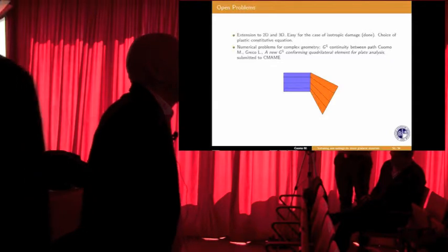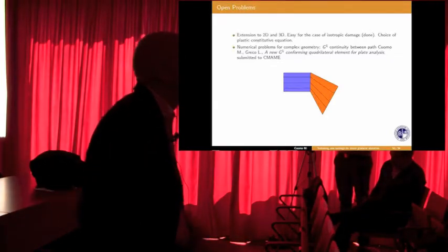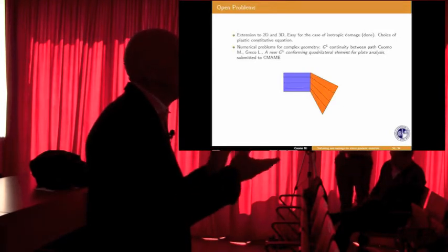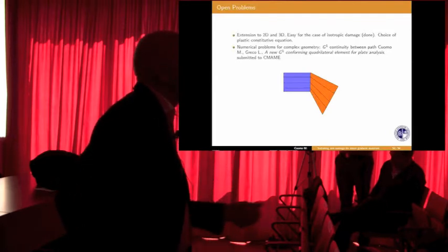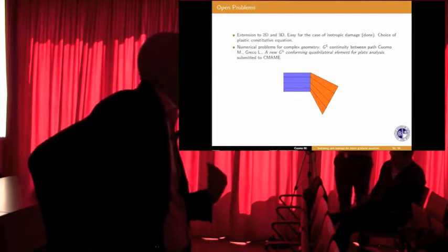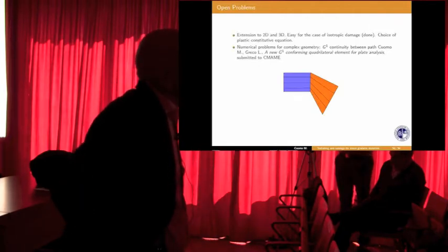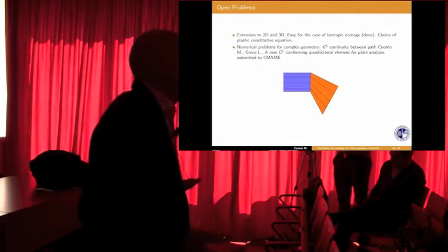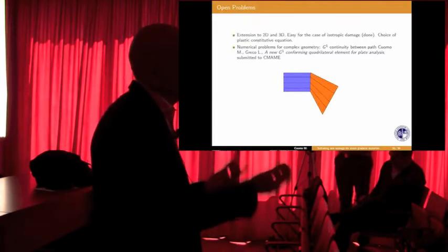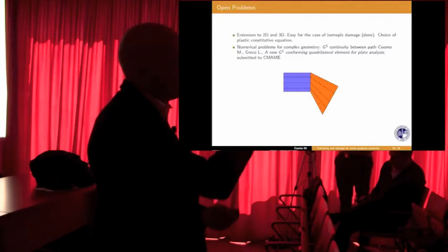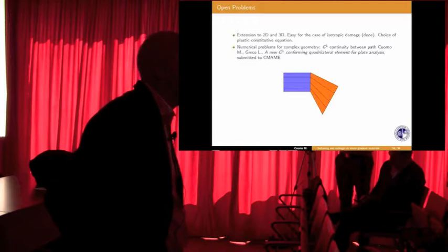I've said that this coefficient has to be strictly larger than 1, otherwise the constitutive equation cannot be inverted. The smaller they are, the sharper the damage. If they are large, damage is softer. It's always difficult to set, so it's the easiest way to do it. Typically we take 1.5 or 2, and then you should fit it experimentally.